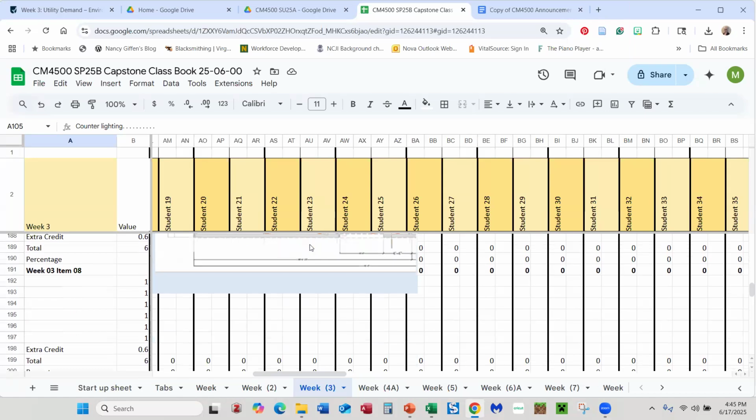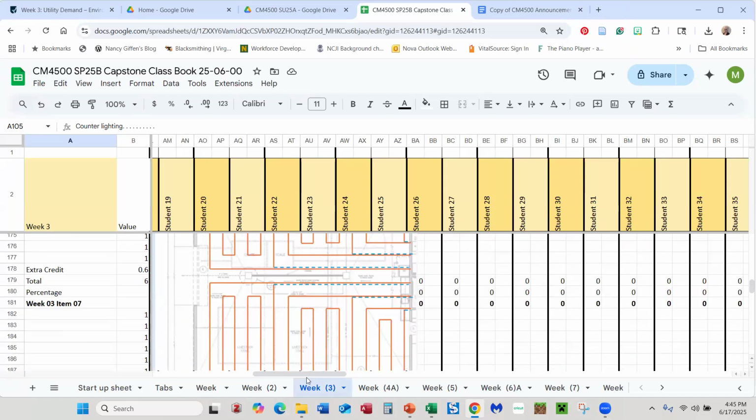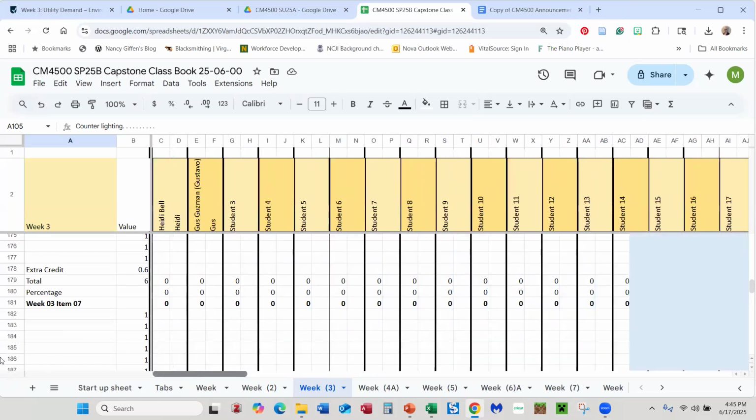I've never seen those mechanical radiant systems before. I've heard of them, but I've never seen them in a project. Yeah, they're a pain. They're better in something like concrete that you pour. They're bad in something with a wood overlayment, because someone always drives a nail through the tubing.